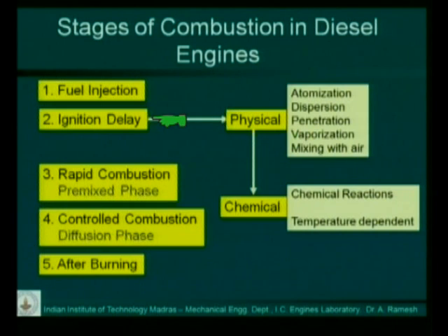without burning is called the ignition delay, and this ignition delay can be broken into two phases. One is physical and the other one is chemical. The physical portion involves all the physical aspects like atomization of the fuel, dispersion of the fuel, then its penetration, vaporizing, mixing with air, and getting ready for combustion, even getting heated, its temperature being changed and all that.